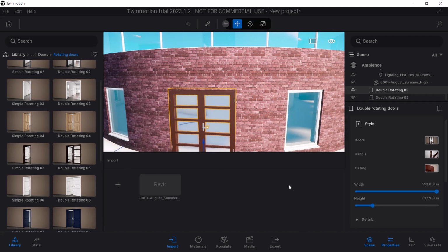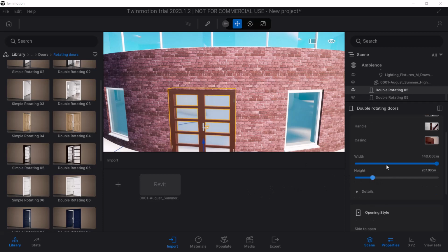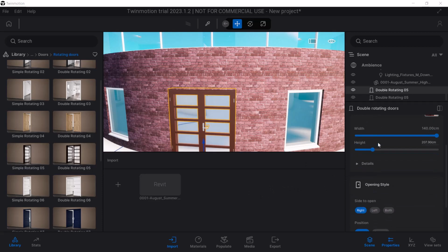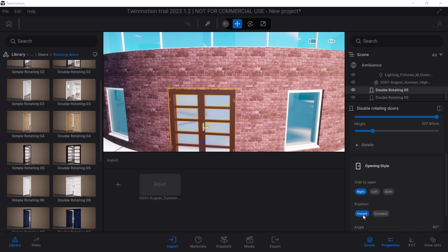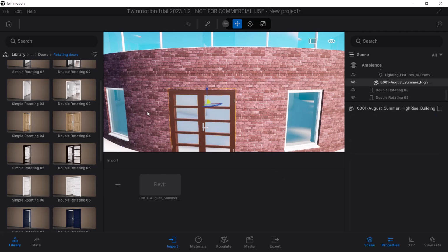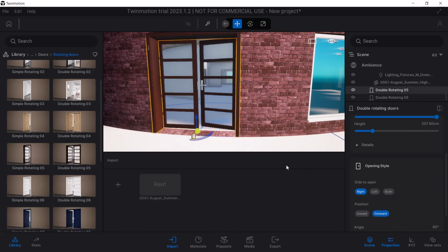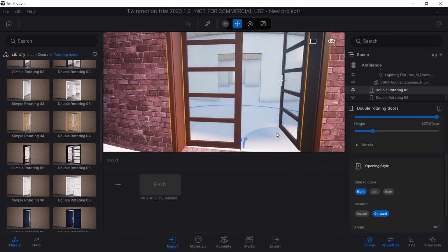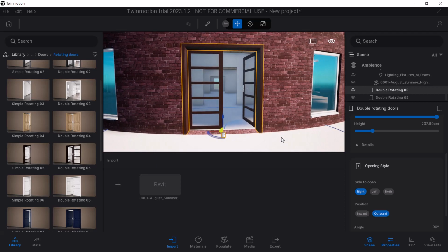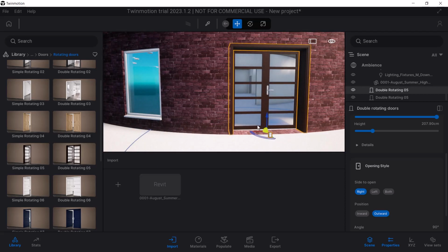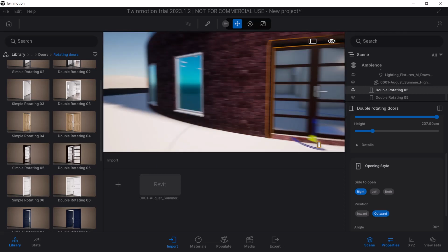So if I go on to select this door now, I can scroll to the door properties and find anything that helps me go on to change this. So the door opens inward, so since it's inward and it's appearing outward here, we just have to click the opposite. So open outward, and then yeah, it now goes the other way. So that's basically how the door works in this situation. I should try to flip this door, but that's just going to make this video excessively long.